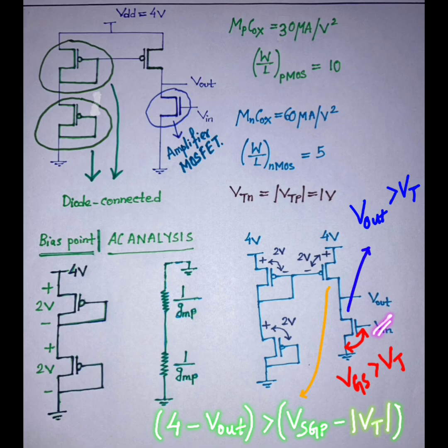And it is already set in the bias, means already set in the saturation point, assume it. And the voltage also at the NMOS is set in such a way that this NMOS will also be in saturation. Okay, and this PMOS, how can you say that it is in saturation? If your 4 volt minus Vout is greater than your overdrive voltage, then it will be in saturation.